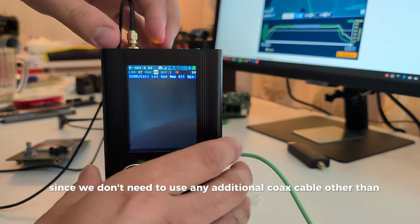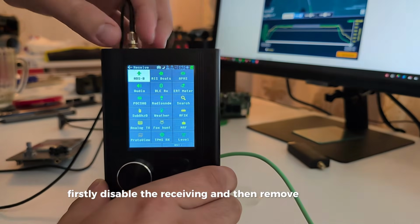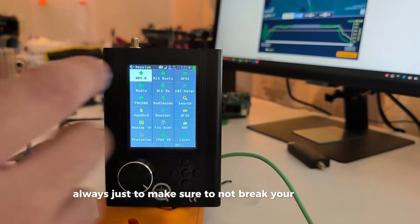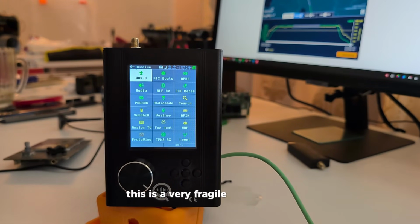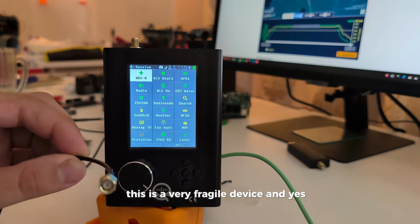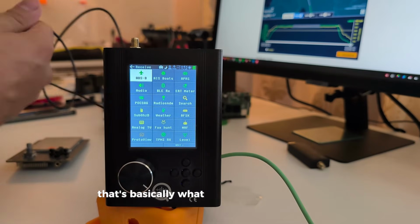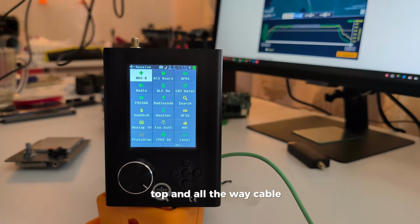Let's actually quit. Firstly, disable the receiving and then always remove the antenna, just to make sure not to break your HackRF. This is a very fragile device. And yes, that's basically what the antenna is.